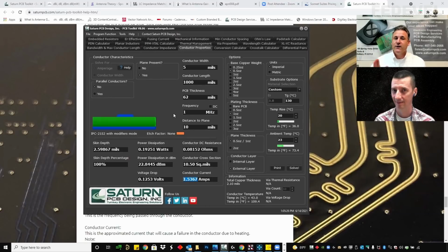And keep in mind, this was multiple people soldering them. These are high-end vendors. It's not Joe Blow's assembly shack. They had real issues with quality until I started pulling some of that copper away. So adding a plane definitely pulls a lot of heat away from your trace.